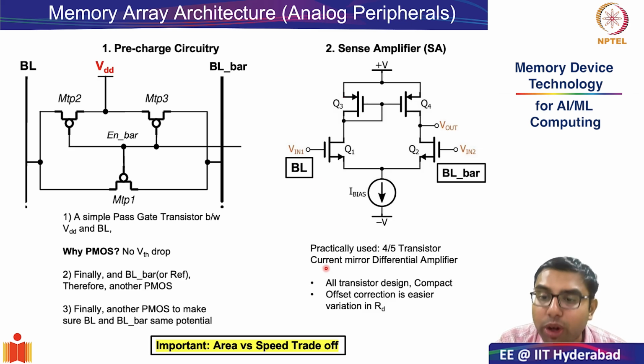This is important because making accurate resistance on CMOS lines is very difficult. Making transistors which are reliable and identical is much easier. The area occupied by a reasonable resistor is much larger as compared to a transistor.